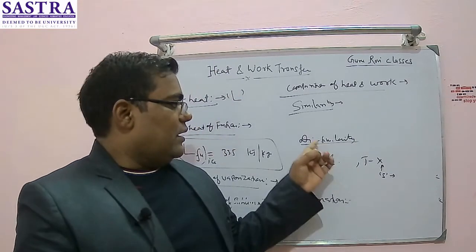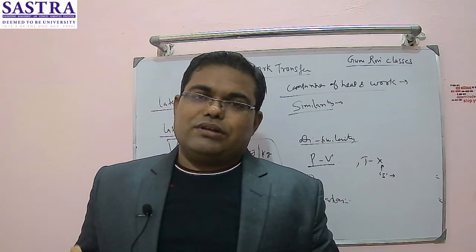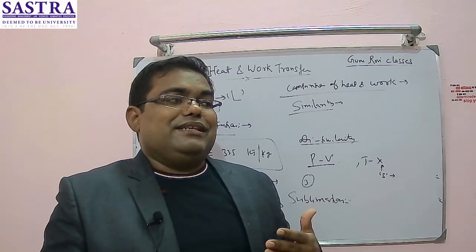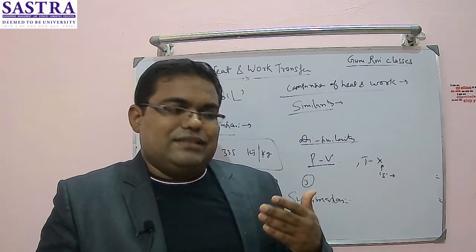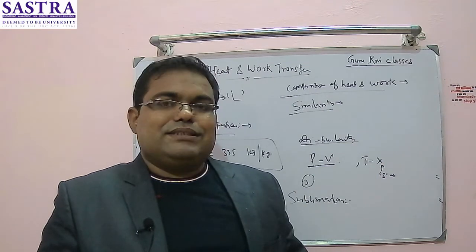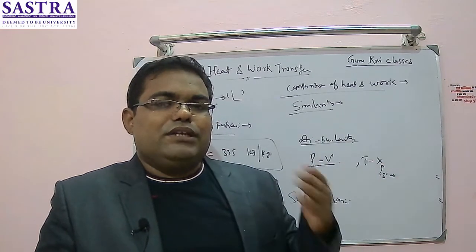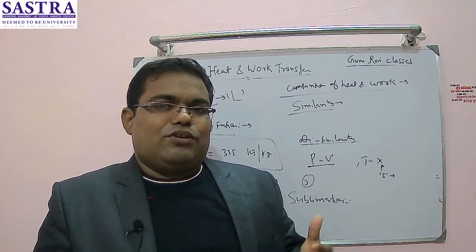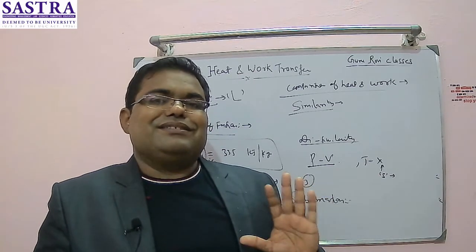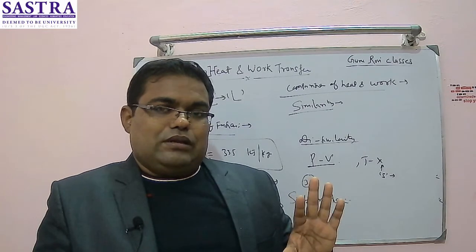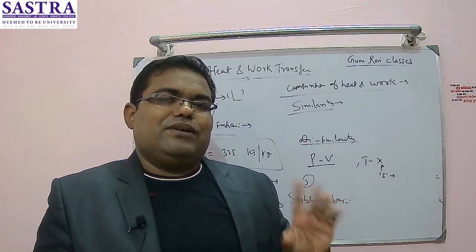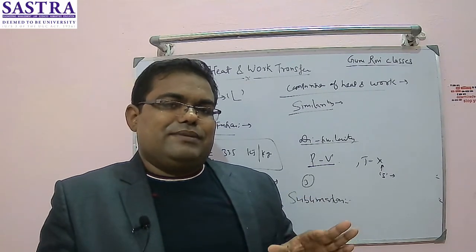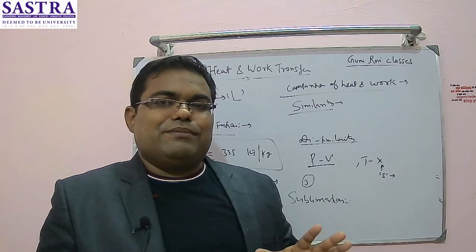Similarity we have seen, both are boundary phenomena. They will occur only at the boundary. If somebody says that I am able to sense the work when I was within the system, that statement will be wrong, because when you are inside the system you will not feel anything. If you are at the boundary only, you will be able to sense the changes which are happening to the system. So both are boundary phenomena. That means they are the form of energy in transit. Basically any closed system will be interacting only via these two modes of energy interaction. Sometimes work transfer will happen, heat transfer will happen, or both may happen across the system boundary.